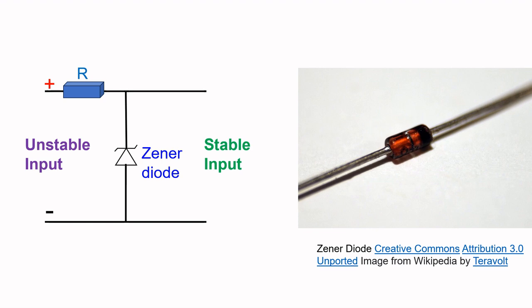As Zener diodes have both voltage and current limitations, this simple regulator is usually employed only in low voltage, low current circuits. This method is also inefficient as it dumps excess current which is not available to the load.